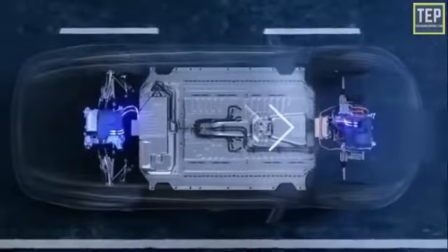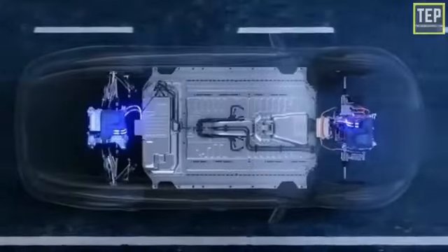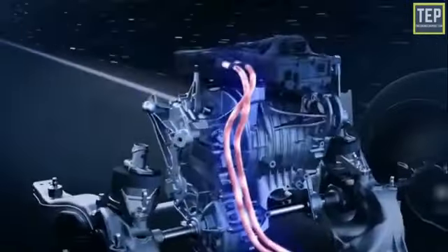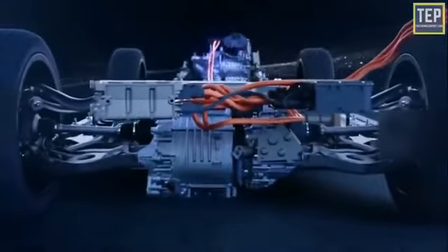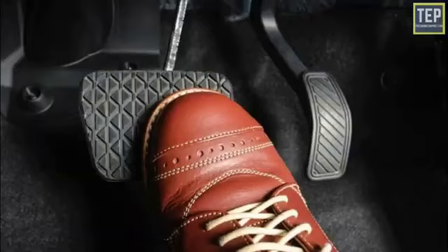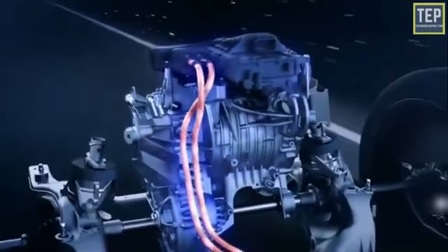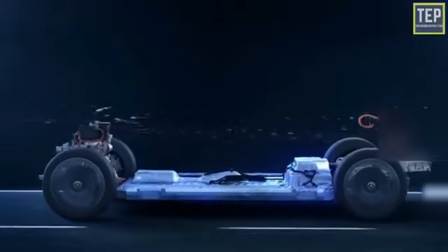Power is converted from the DC battery to AC for the electric motor. The accelerator pedal sends a signal to the controller, which adjusts the vehicle's speed by changing the frequency of the AC power from the inverter to the motor. The motor connects and turns the wheels through a cog. When the brakes are pressed, or the car is decelerating, the motor becomes an alternator and produces power, which is sent back to the battery.